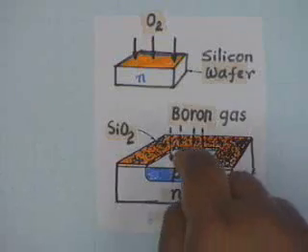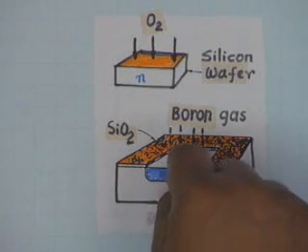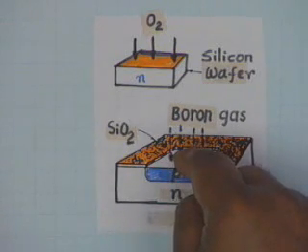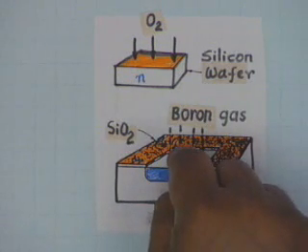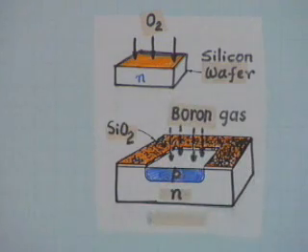It is as if you take a piece of blade, if it was a large dimension, and scratch off some silicon dioxide, so that silicon is now exposed. Is this clear? The rest of it is silicon dioxide, but a part of silicon is exposed by means of etching, not by a blade, but by passing an etching agent, all right.